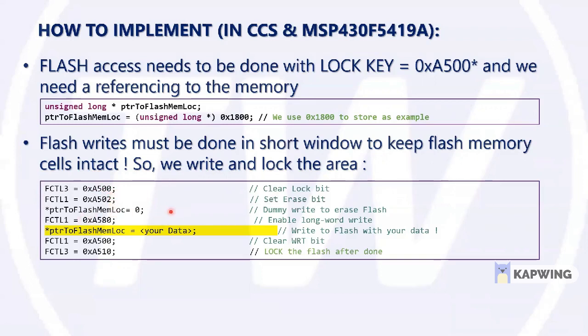So remember, if you're using the SRAM area, you have to erase, or even if you're using the flash area, most microcontrollers' flash supports erasing of the entire flash segment before you write any data into it. So if you're using, for example, segment A, then you have to erase the entire segment A and then load data into segment A. This is a bit tricky when you need to implement it in place of your I2C EEPROM, where you can just keep on writing to the memory area. But I think it's not that much of a challenge either. You can manage it as compared to the hardware cost that we have.